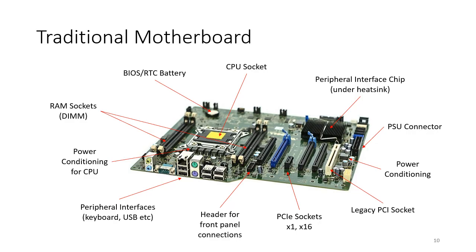But what you can see in the middle there is the CPU socket. That's where the CPU will be plugged in. On top of that CPU socket, there would be a heatsink. If you're building a gaming computer, that heatsink could be a fairly substantial lump of aluminium with various vanes, and then it might also have one or two fans bolted onto it as well. That heatsink is the primary way of removing heat from the CPU when it's under power. In very advanced systems, you might find that the CPU heatsink is the case itself. I've seen that for various industrial PCs where you use the case of the industrial PC as the heatsink.